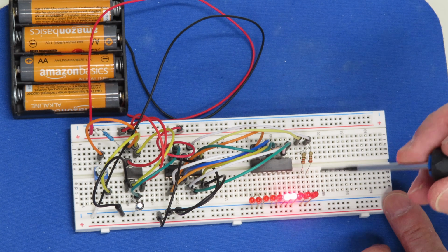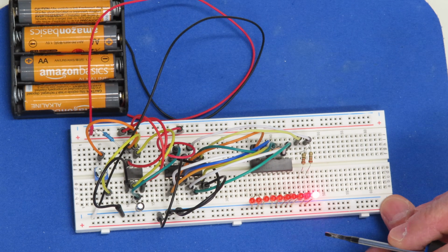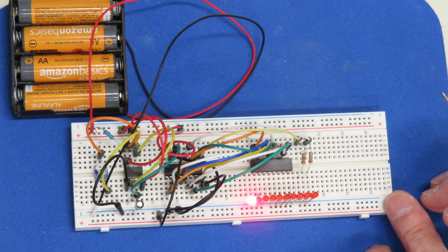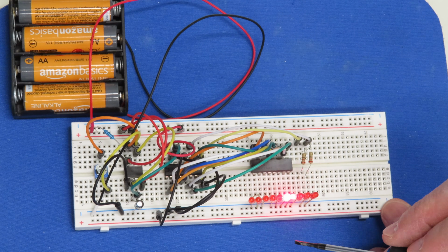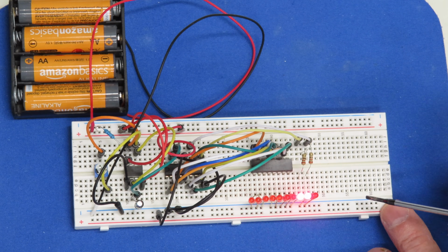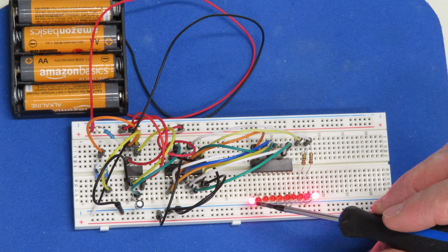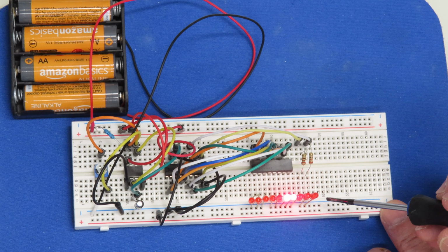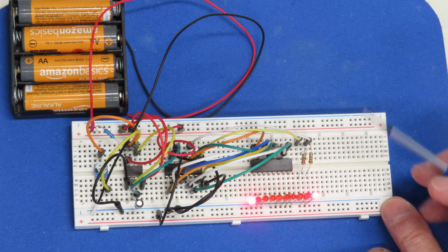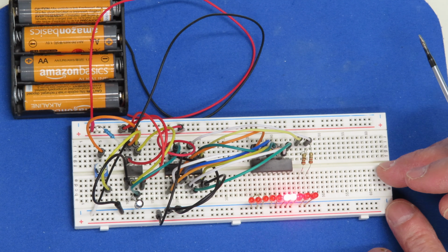And you could also, instead of just using LEDs on the output, this could be opto-isolators driving something bigger. You could even use solid-state switches and use full-size lights for this. And if you wanted to extend the chasing effect in that way, you could put another string of lights after that. You could just have 2 things chasing, so this first light would go and also drive an 11th light, the second one driving a 12th one, etc. There's a lot of possibilities over here as to what you could do with this very basic chaser design.